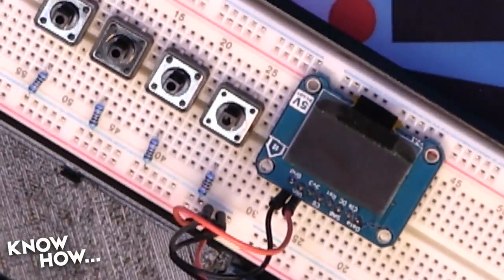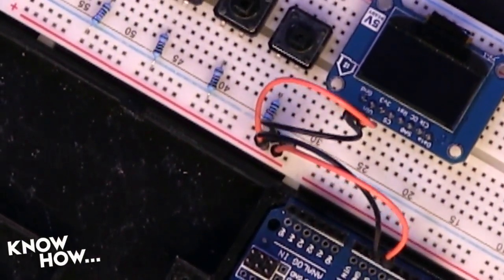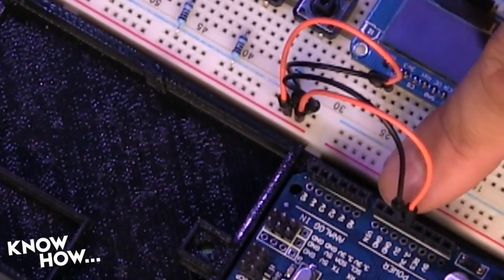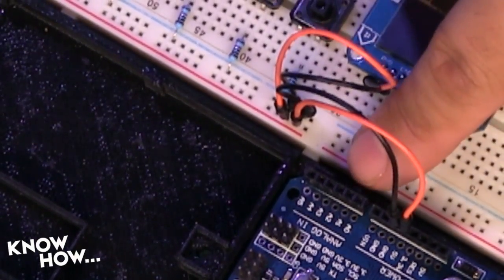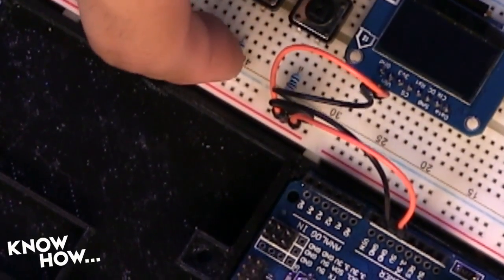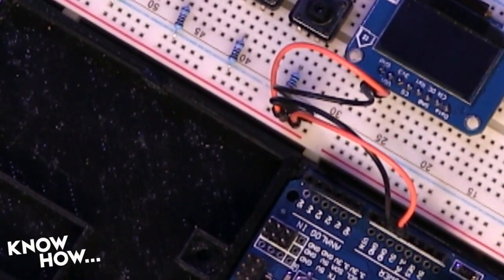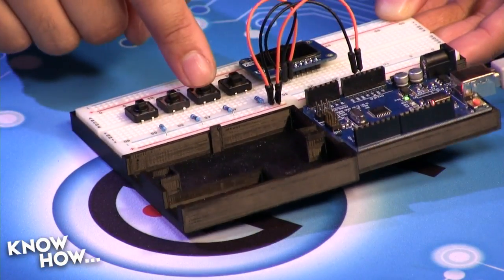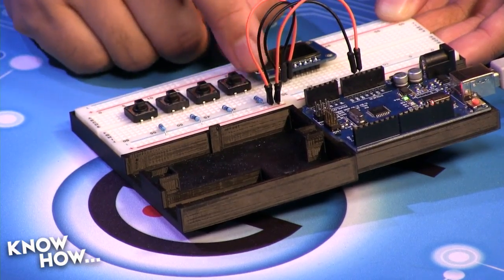So here's, I'm sorry if you're an audio listener, what I've got right now is I'm going from the 5-volt pins, so from ground and 5-volt into my breadboard. These lines at the top, they're the same all the way across. So all of those top pins are now 5-volt, and all the blue pins are now ground. Now, the reason why I'm going into the breadboard is because eventually I'm going to have to pull power over so that the buttons work. But right now, I just need 5 volts to make the screen work.